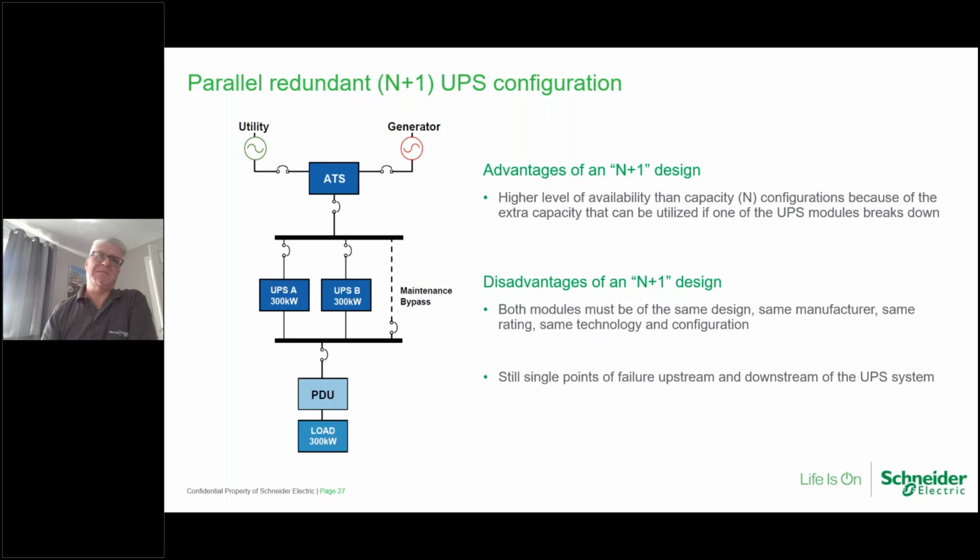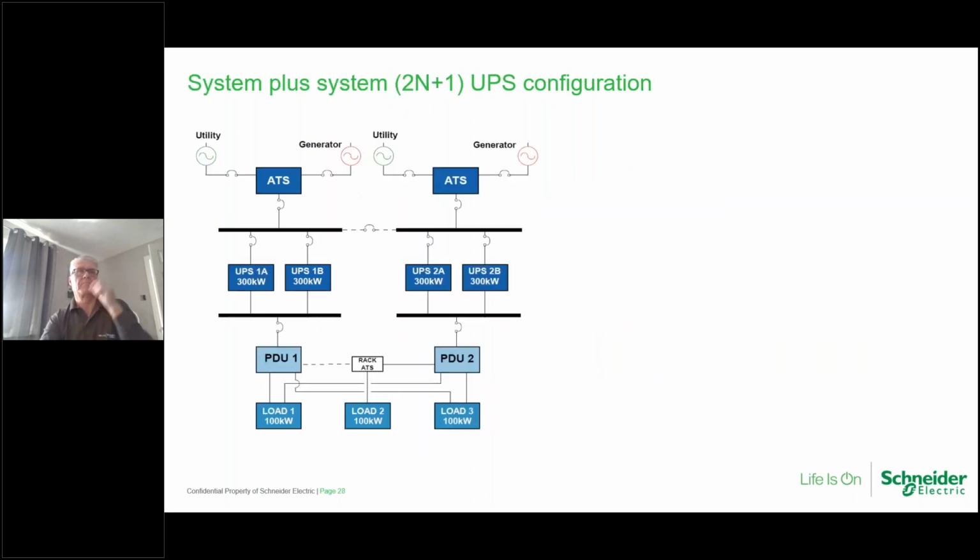Disadvantage is that yes, they have to be the same design and manufacturer. You can't just mix and match UPSs, same technology and configuration, because we need to be able to synchronize the outputs of these to support the load. And as I mentioned, there are potential single points of failure, but that's part of the assessment of the system.